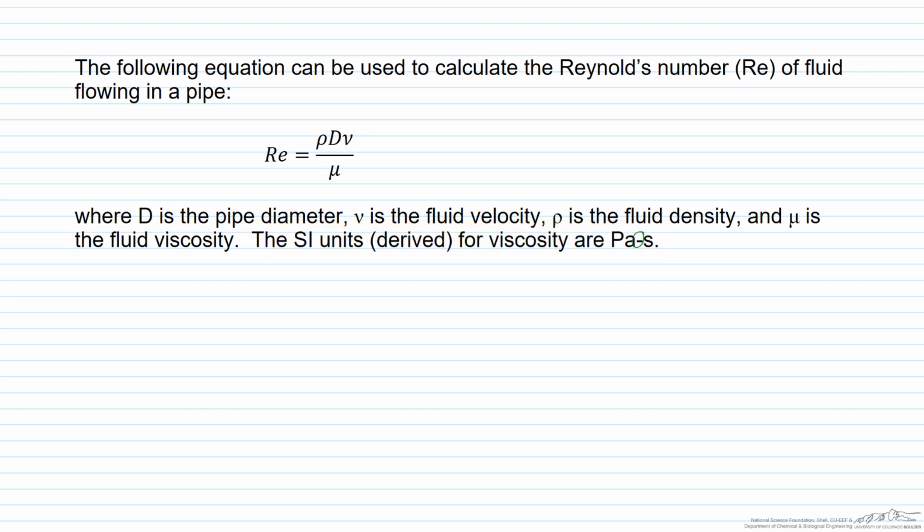So let's take a look at the right-hand side of this equation. Rho is density. Density is mass, and I'm going to write this as big M. What I like to do is write Reynolds number, and put in square brackets an equal sign, which has units of, or has dimensions of. So it has mass, right? Density is mass per volume. Volume is a length scale cubed. So density is mass, big M, don't confuse that with meters, mass divided by length cubed.